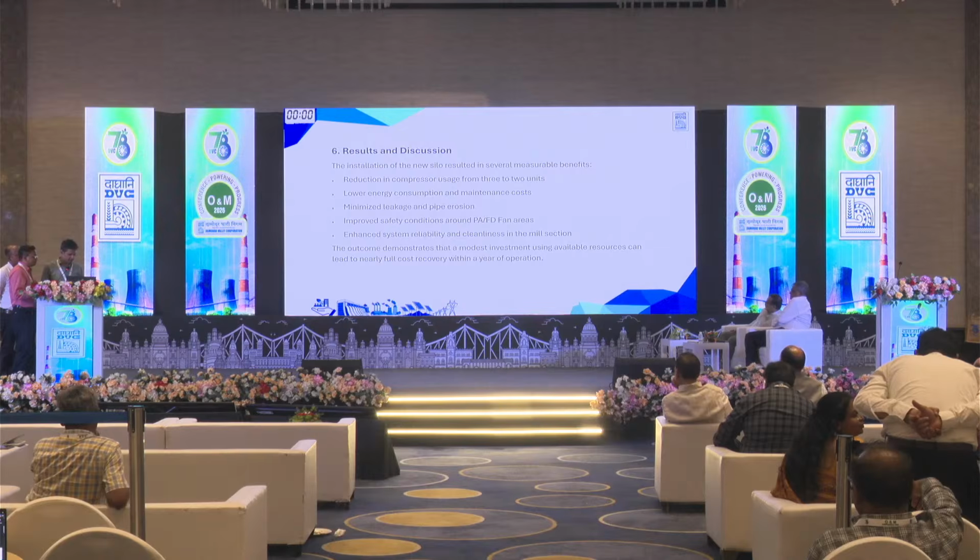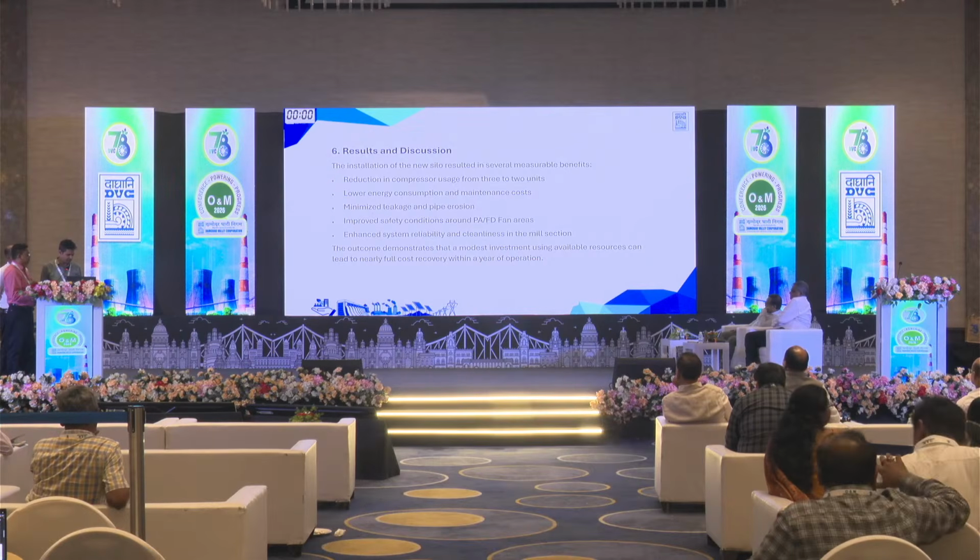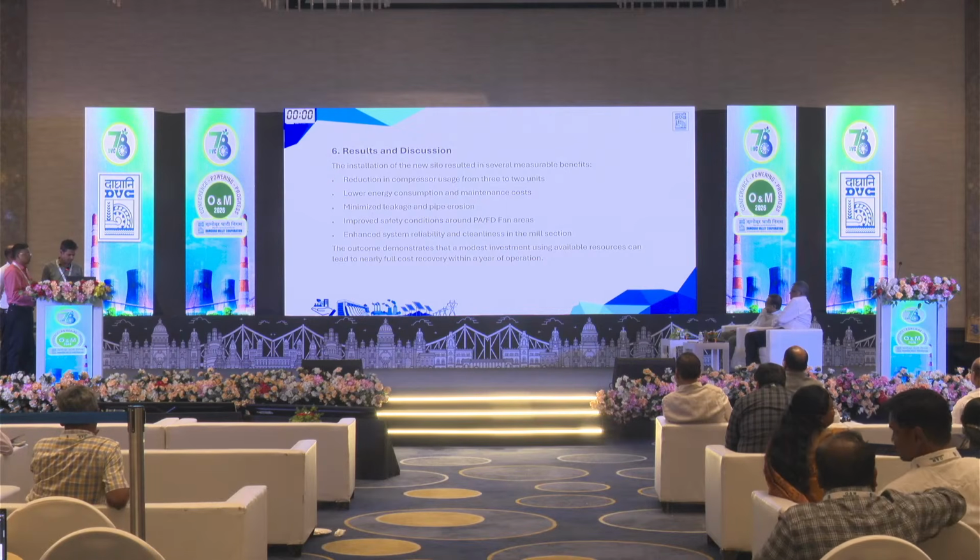Results and discussion. Due to installation of the new bunker, there is a reduction in compressor usage from 3 to 2, lower energy consumption and maintenance cost, minimized leakage and pipe erosion, improved safety condition around the PF and FD fan area, and enhanced system reliability and cleanliness in the mill area.